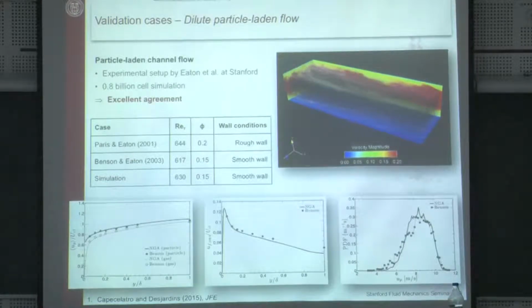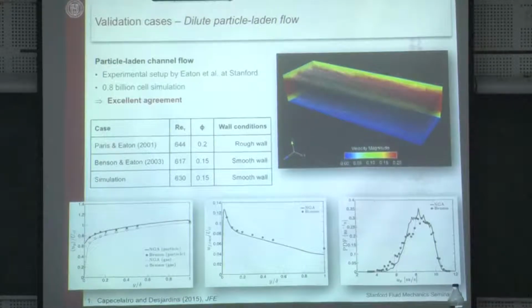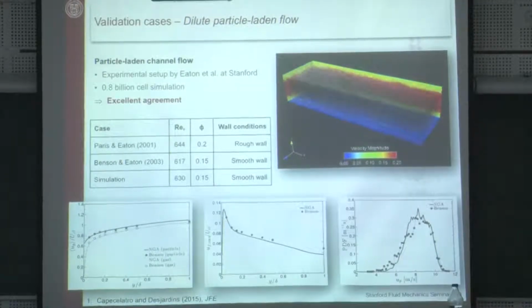Yeah, we figured out afterwards that after running this channel for a long time, our walls were crazy rough. So this is not a smooth wall experiment, this is a highly rough wall experiment, just because the accumulation of collisions of the particles with the walls ended up creating a very complex roughness pattern all along the experimental apparatus. So they fixed that. They went to a tougher metal for the wall. They changed regularly their plexiglass for visualization. So anyway, they figured this out, and they recreated an experimental data set with smooth wall afterwards, and so that's what we're using. As soon as we went to this new data set, everything started matching beautifully.